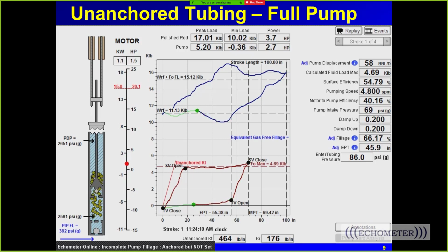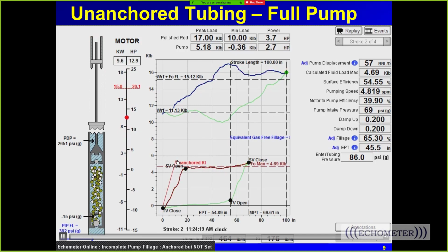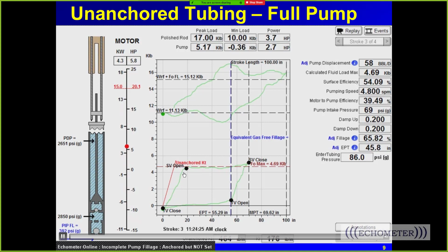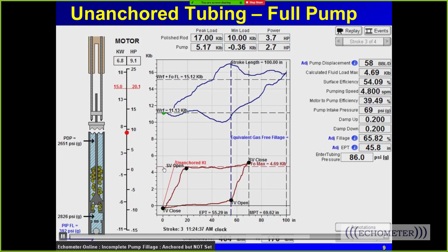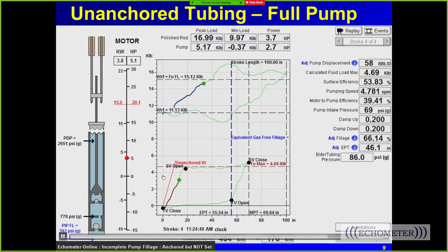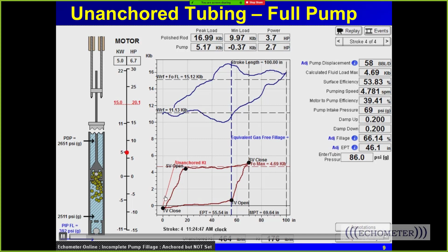What you should look for is this line right here. You should calculate this line based on the tubing length, the tubing diameter, and the spring constant. If you're unanchored, then the slope of your pump card should be on the right-hand side of this line because of slippage. If the pump card load line, when it's picking up the fluid load, is over here between the vertical line, anchored tubing, and the unanchored tubing line, then it's most likely just slippage, and you probably ought to investigate your pump clearances, your plunger size and your plunger length, because it's more likely due